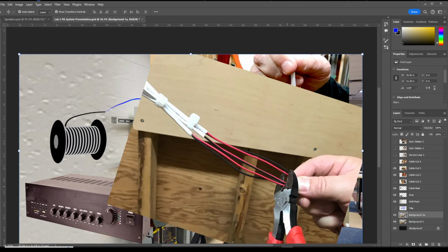I noticed that some of us cut this right close to that jacketing because, well, we need to save our planet. Yes, we need to save our planet, but we're not going to save our planet doing this. You're just going to make our job more difficult, and actually we can make things worse for our planet, because if we cut the wire too short, then sometimes you're going to have no choice but to re-pull another wire. So things are going to go to waste.